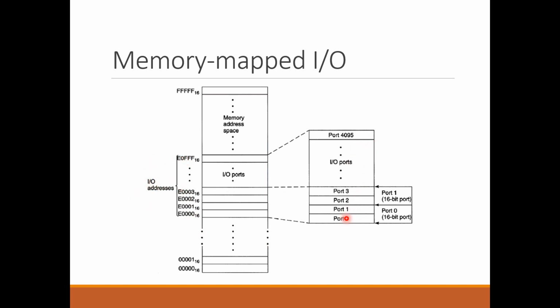So the ports are going to be held inside those memory locations, and the functionality is the same, port 0, port 1, while those two ports can be used to operate as a 16-bit port, while each of them holds only 8 bits of data, or they can be used as 8-bit ports, while the other parts of the main memory can be used for memory purposes.